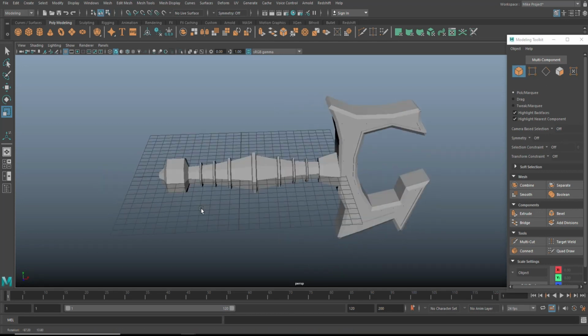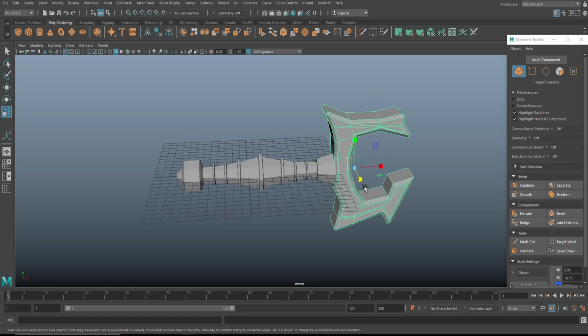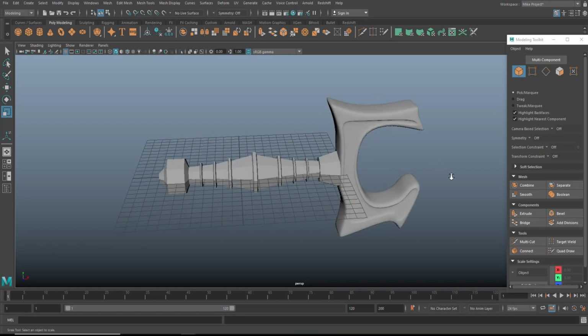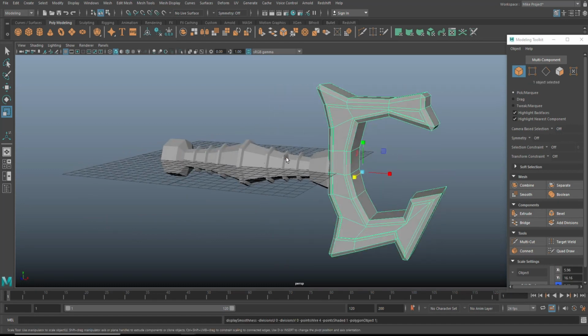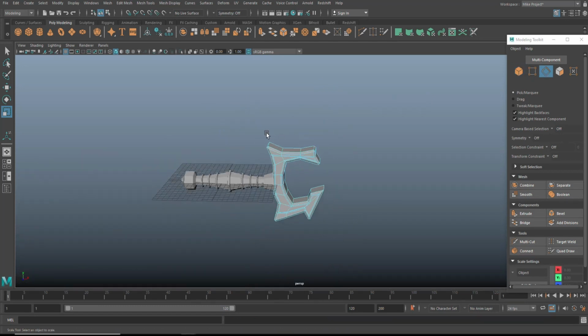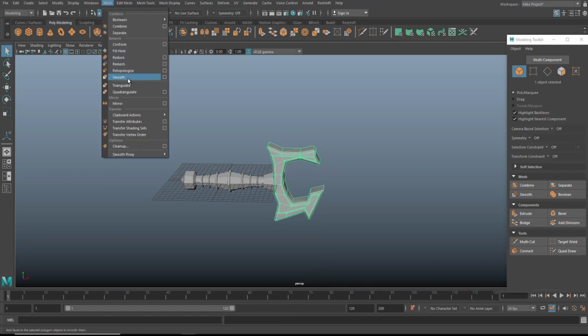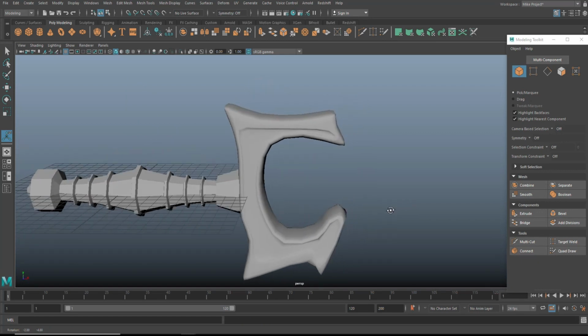Just to add some detail. Okay. Yeah, that works. Okay, so I'm happy with this guy. I'm not sure whether we'll smooth it. I think we will, because that kind of looks cool. So what we'll do here is we'll want to go back, and we're going to go in edge mode. We're going to drag select all of these, and we're going to Control B to bevel 0.001. That's just to harden those edges. And then we'll go in here to mesh and smooth to have a look. That looks kind of cool.